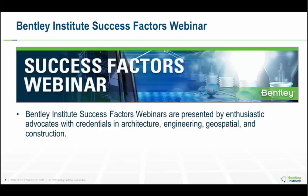So the iterative method, the geometric stiffness method, and the amplification factors B1 and B2 are three very distinctly different methods whose intention is to arrive at the same solution, and very often they will arrive at very, very similar solutions. And so I'm comfortable in most cases using any of those three approaches. Some have advantages over the others.